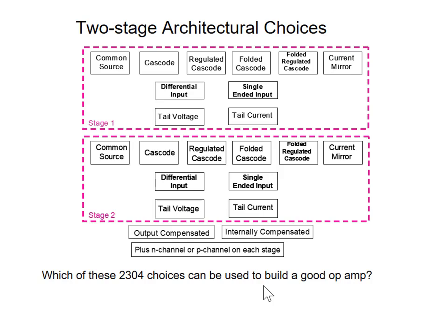What's your application? Good answer. Depends on the application. Can we X out a lot of these? It's possible. No. Yes. Current mirror's not that bad. We just said it didn't offer many benefits, but if M was fairly large, it wasn't much worse either. And maybe it's got good signal swing characteristics, and maybe it's easy to design.